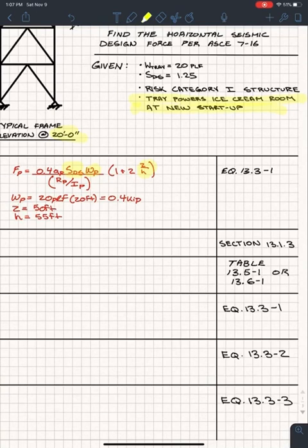So based on the stipulations given, if the component is required for the function for fire life safety purposes of the structure, or it conveys some type of toxic material, it's attached to a risk category 4 structure, and it's needed for continued operation, and then if it contains hazardous substances, you're going to apply 1.5 importance factor. Otherwise, you end up applying a 1.0 importance factor.